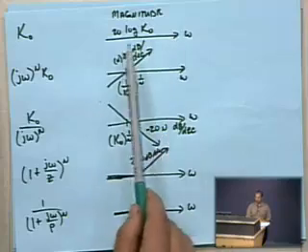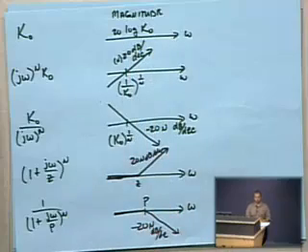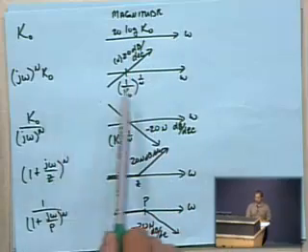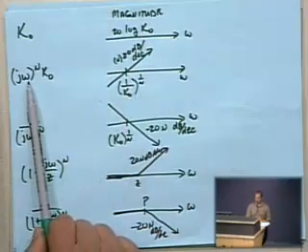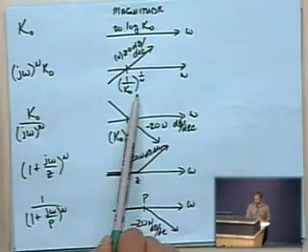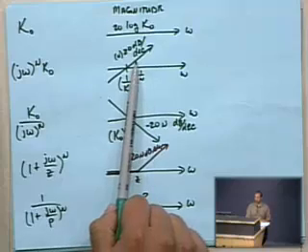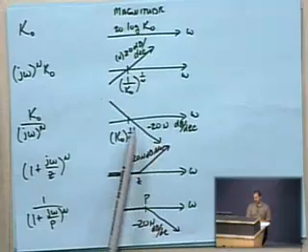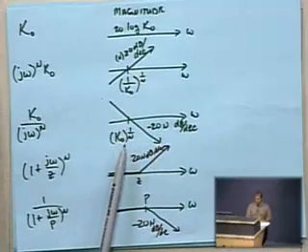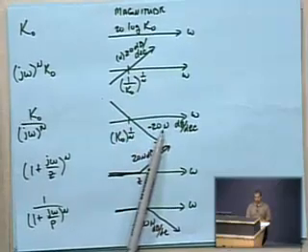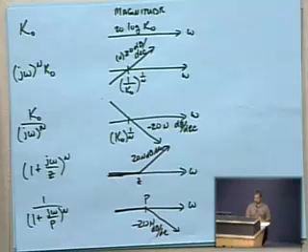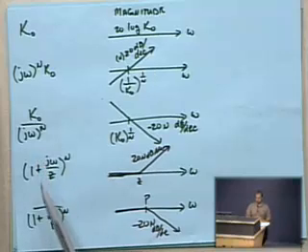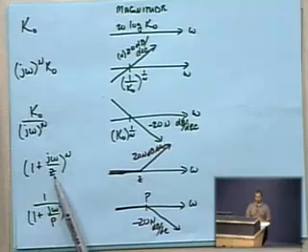The magnitude will be flat for any constant terms. For zeros at the origin, it will cross at this particular spot, increasing at 20 times n dB per decade. For poles at the origin, it crosses the x-axis at this point at negative 20 times n dB per decade. And then our simple poles and our simple zeros are the easiest ones to deal with.